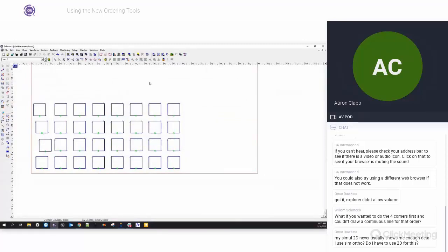So this is the order by line. So the next tool that we want to go over is order by group. Now this one has no check boxes, there's no real tool to click on. It's just a feature that's been added to the background of EnRoute, and it automatically does it based on the actions that you take in the software.